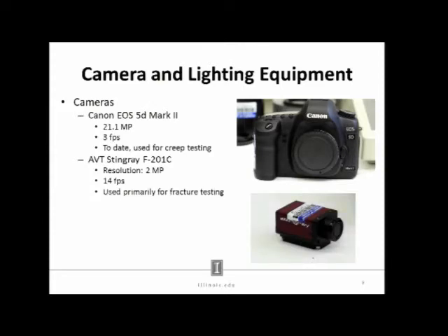Obviously, we do have a drop in the resolution. As for the frame rate, in some digital image correlation techniques they're using cameras that can go thousands of frames per second. We don't need to go that fast. In essence, if we can get 30 to 50 images pre-peak, then we can easily understand what's going on post-peak, when we have maybe a 2 to 3 minute test where, for the most part, those 2 or 3 minutes are all occurring in the softening zone.